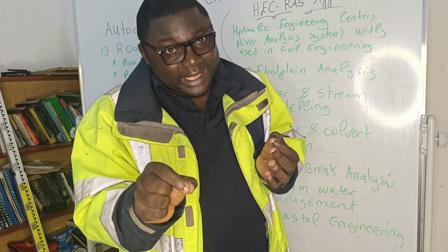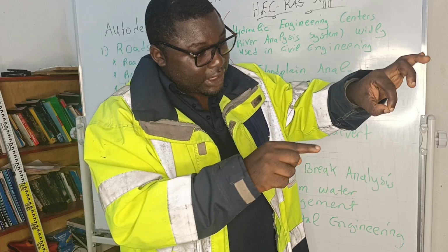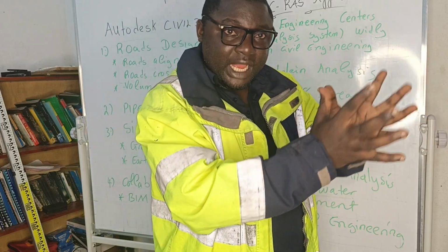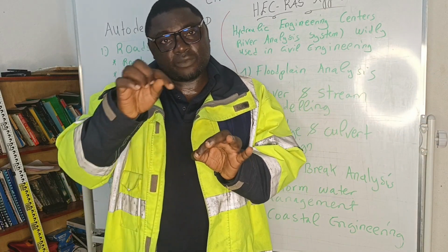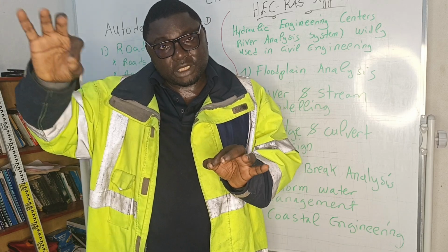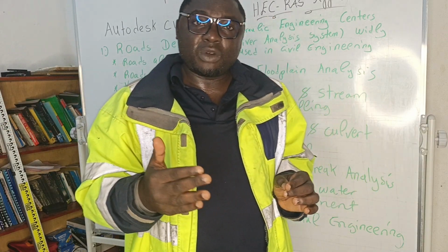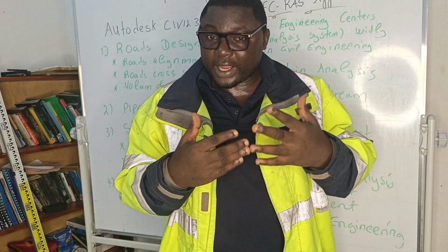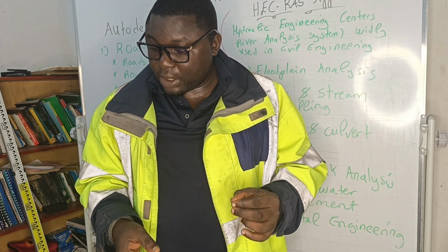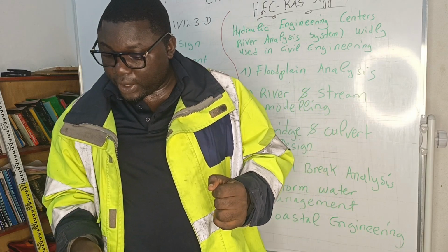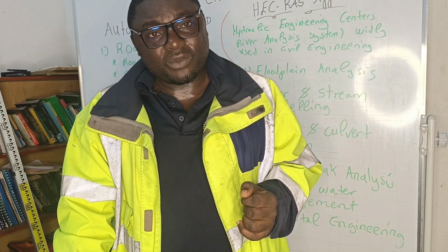X, Y, and Z. Each point is defined by its coordinates X, Y, and Z. That is altimetry. You're the one to go to this field to pick up this data. And at the end of the day, we can use this data to calculate the volume of earthwork, which is very important in engineering projects. Okay, so under altimetry, we are going to deal with leveling. So leveling surveys, chapter 1.